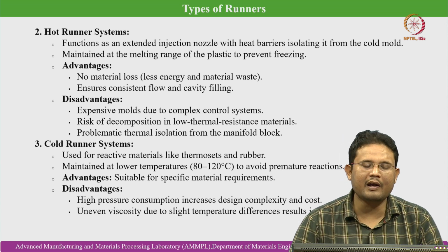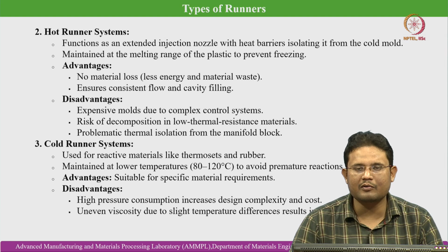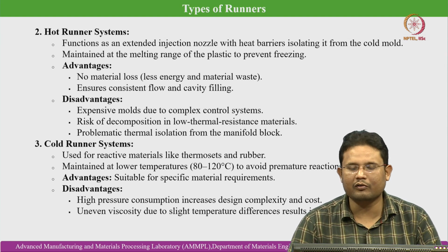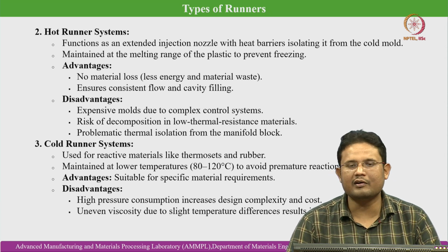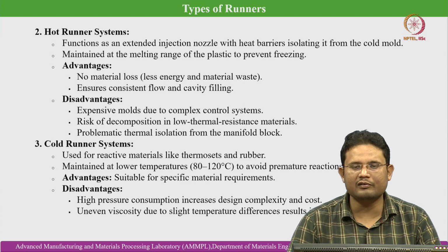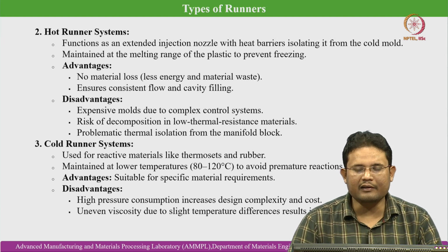Generally, in case of polymer injection molding, thermoplastic polymers are used, and also in case of MIM and CIM, thermoplastic polymers are generally used as binder materials. Hence, the feedstock material in which the polymer part has solidified in the runner can be reused by remelting the binder component.